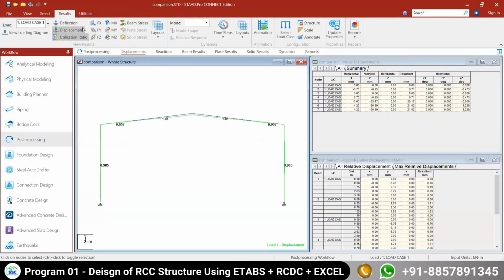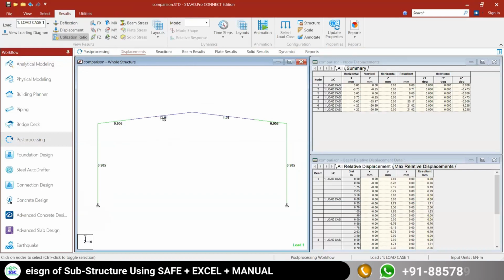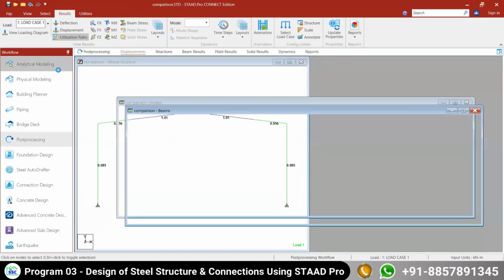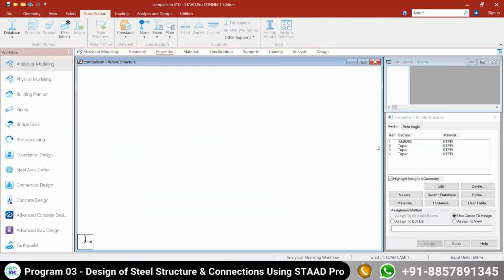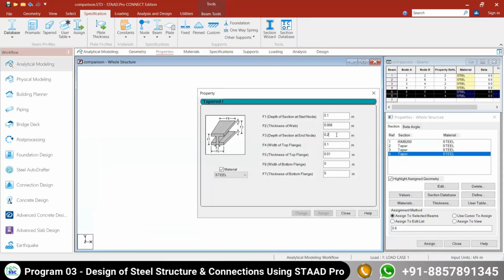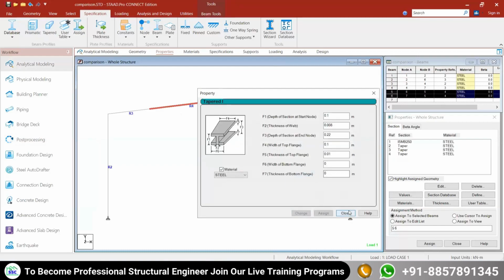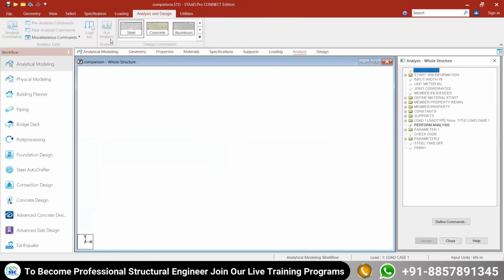I'll check my utilization. See, now utilization is, this is 98%, this is 95%, but this is slightly failing, 1.1. So I have decided that I want to start it with 100 and end it with 200, but it is slightly failing. So what I can do is I can slightly increase it. So this is what we do. Instead of 200, I'll make it as 220. Okay, we'll run it again.